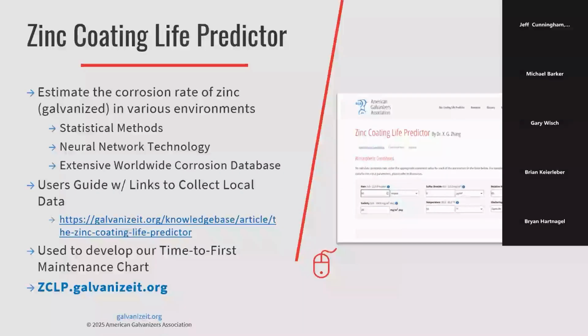It is not developed off of spray testing, which is critical because salt spray testing does not allow the zinc patina to develop. And the zinc patina, the zinc hydroxides and zinc carbonate, develop on the surface and really lengthen the life of that galvanized steel, giving it that 70, 100-year design life. So this is all real world data.